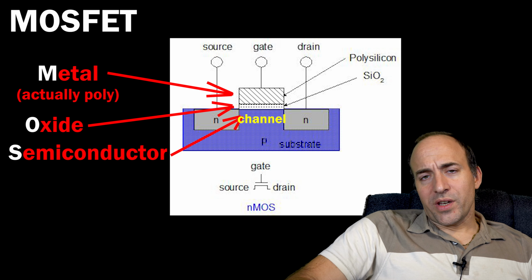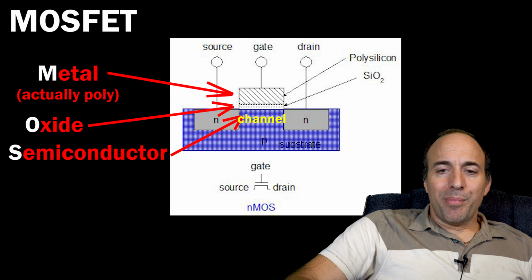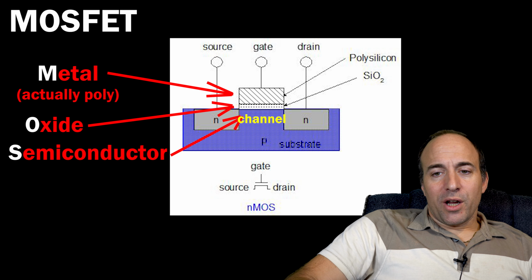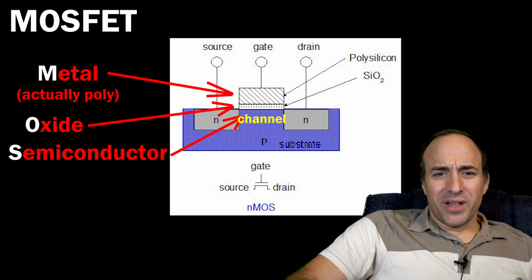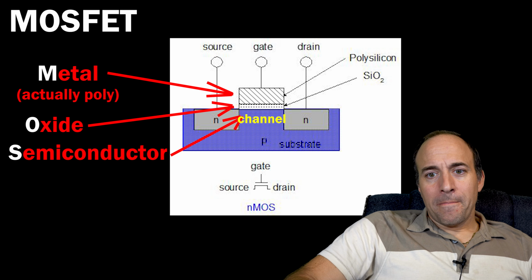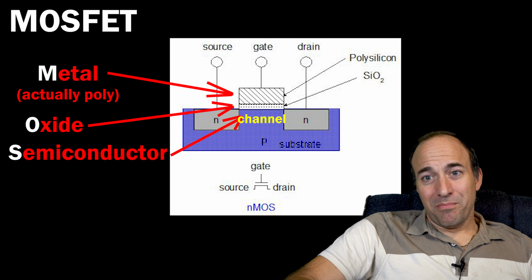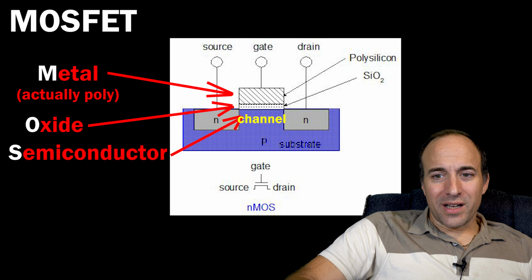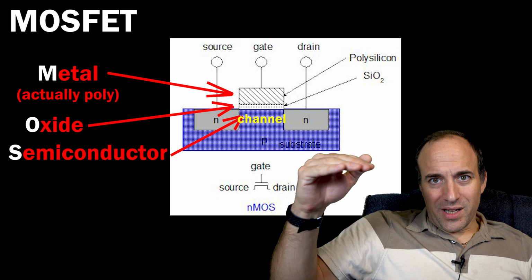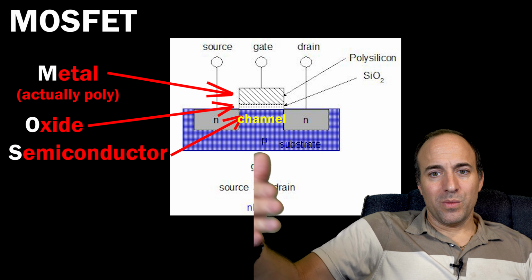And so silicon dioxide, or sometimes just called glass, is used as insulating layers on a chip. And then above that insulating layer is a layer of highly doped polycrystalline silicon called polysilicon, and that's called the gate. Now, in the past, instead of the poly, there was a layer of metal there, which explains the anachronistic naming of MOSFET. So metal oxide semiconductor, that's actually naming the materials from top to bottom as compared to bottom up, which is what I just did.